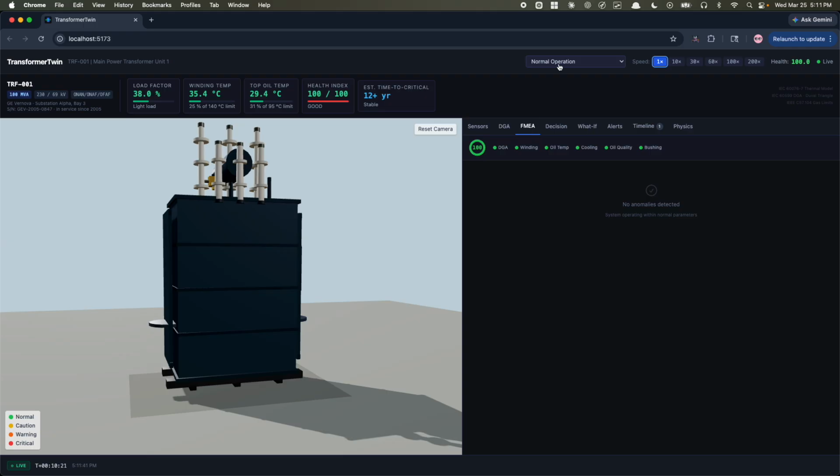Now, the main killers of transformers are like when a hotspot develops. This occurs when there is high load or cooling failure. The paper degrades, insulation fails, and a short circuit eventually develops. There is the arcing event, where electric discharge inside the oil instantly destroys the insulation and may cause the tank to rupture as well. There's partial discharge, which slowly erodes the insulation over months, cooling failure, paper degradation, and oil contamination. Now we can start by simulating some events.